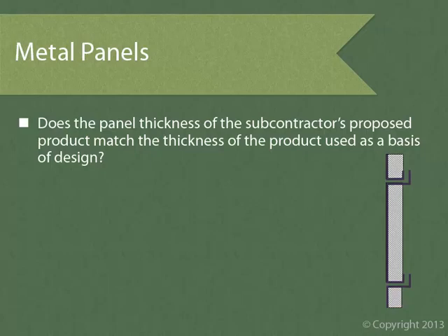Before allowing a different thickness, be sure it will work everywhere, including at windowsills and with respect to the interior face wall. For instance, if the exterior wall is a single stud construction and the interior side of the studs is to receive a gypsum board finish, shifting the studs in or out might cause a big dimensional problem on the interior of the building.